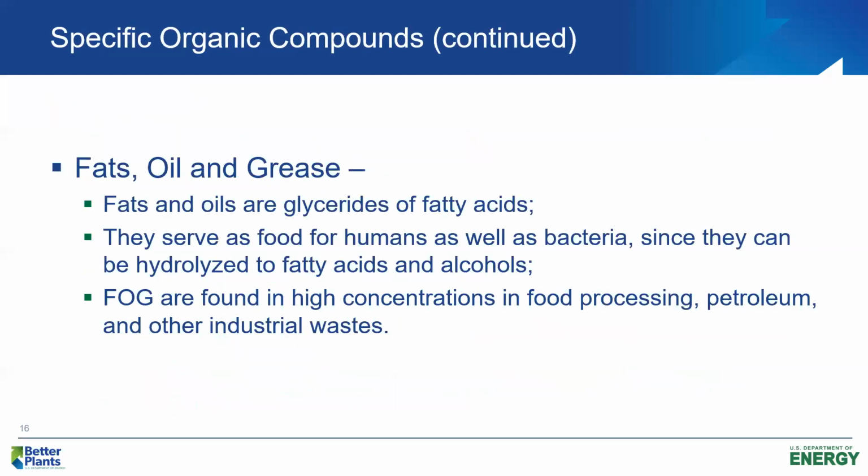Fats, oil, and grease, another constituent I'm concerned about in municipal wastewater. Typical concentration in medium strength municipal wastewater is about 20 milligrams per liter, and usually at that concentration, it doesn't cause us a lot of problems.